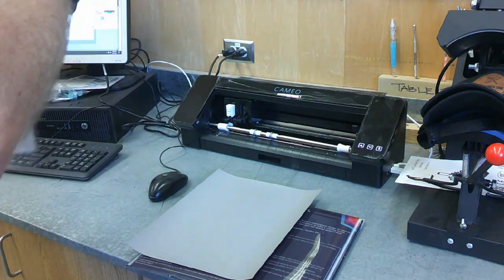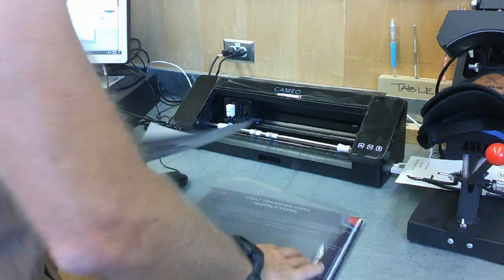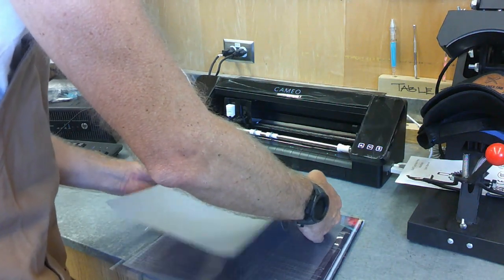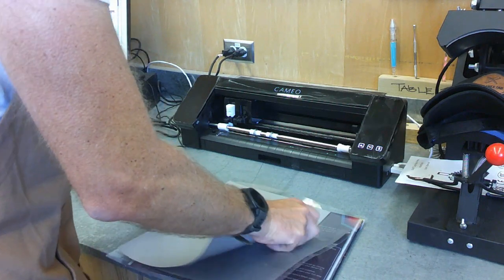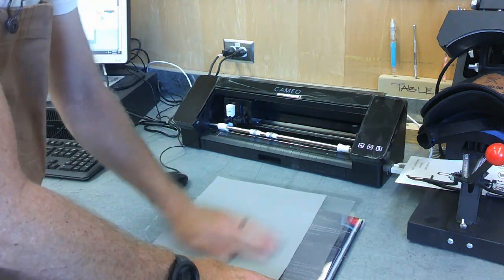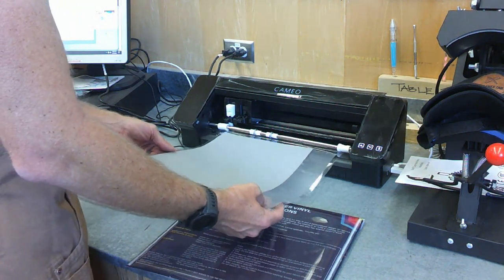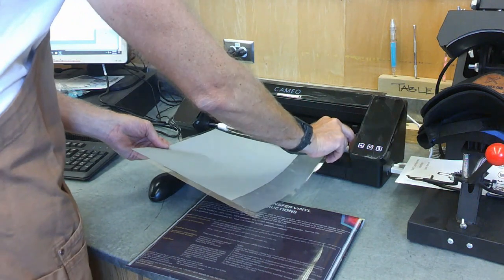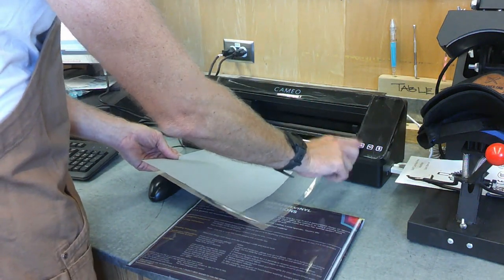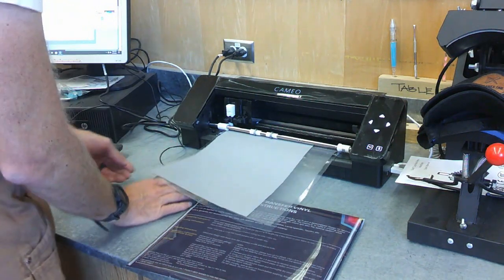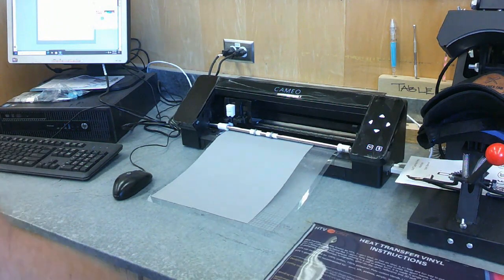So some materials are able to cut without it. This is a little bit sticky. You're going to place it on the mat. It doesn't have to be lined up perfectly, but do what you can with it so you don't waste material. Make sure that it's down there, and then you're going to feed this into the rollers. There are arrows here that show you where it should be set up, and then you hit the up arrow to make it go in, and that will bring in your material. So that's basically all it is, ready to go on the vinyl machine.